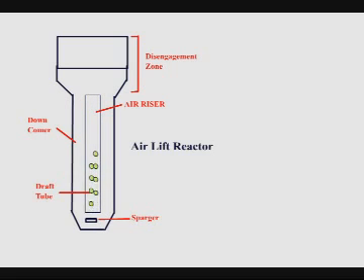Rising bubbles in the air riser cause the liquid to flow in a vertical direction. To counteract these upward forces, liquid will flow in a downward direction in the downcomer. This leads to liquid circulation and thus improves mixing efficiency as compared to bubble columns. The enhanced liquid circulation also causes bubbles to move in a uniform direction at a relatively uniform velocity. This bubble flow pattern reduces bubble coalescence and thus results in a higher oxygen transfer rate as compared to bubble column.